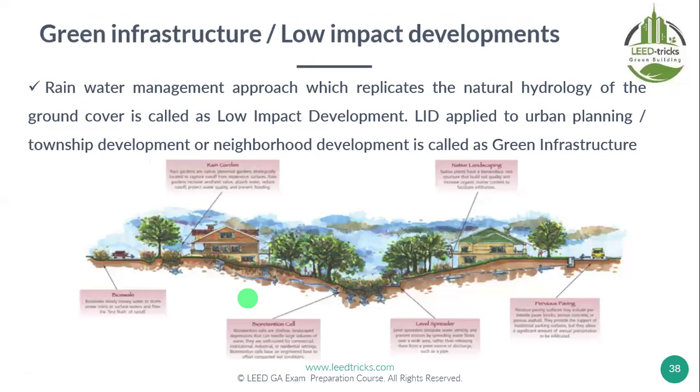First of all, strategies where you have a space, land available, especially in rural areas, not in urban areas. In rural areas, it's logical to use non-structural strategies. We call it green infrastructure and low impact development. So what is green infrastructure? Something like this. If there is a road here, I will make a drain, and the drain will send water to a green area here where it will infiltrate.